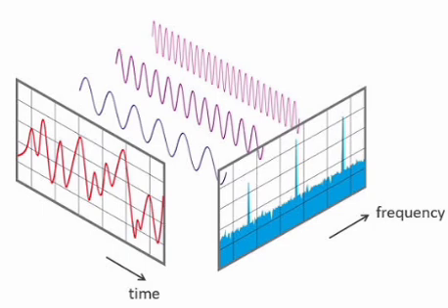Time scaling: x of a t equals 1 by modulus of a X of s by a, with scaled ROC. Conjugation: x conjugate of t has Laplace transform X conjugate of s conjugate, ROC is R. Differentiation in the time domain: d by dt of x of t equals s X of s, ROC at least R. Differentiation in the s domain: minus t x of t equals dX of s by ds.